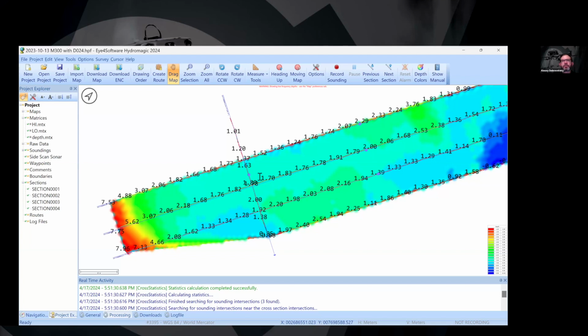So in normal conditions, if data was collected following our recommendations, positioning error or displacement of the Echo Sounder will be around 30 centimeters. It is pretty much inside of all possible requirements. So again, a question about the width of the scan. It is single beam.